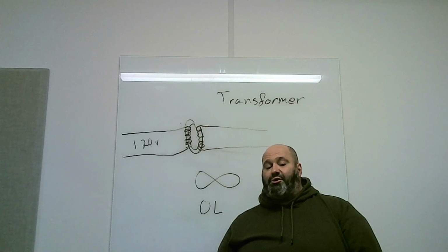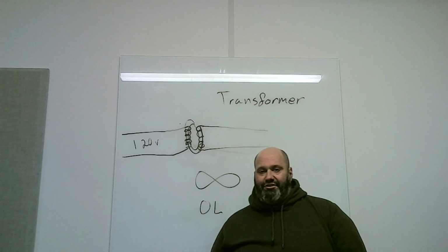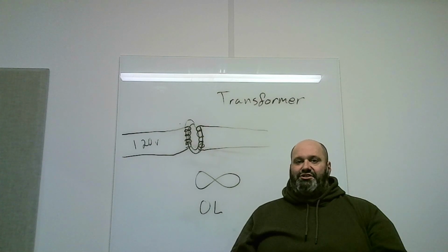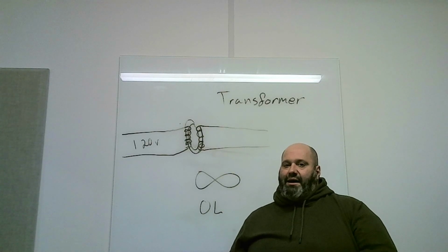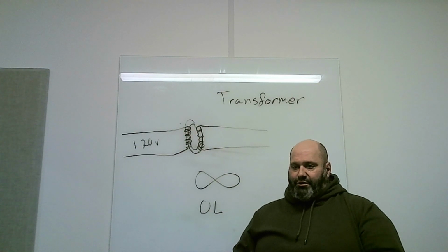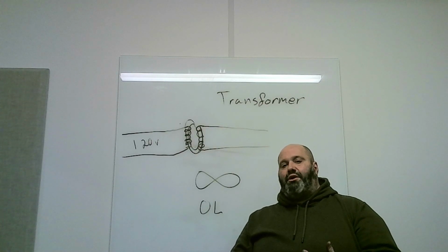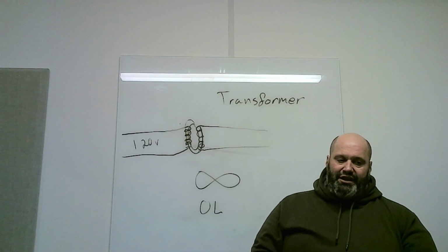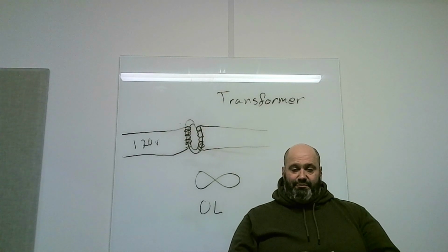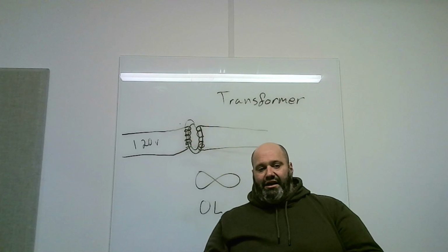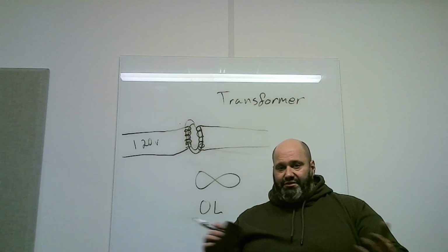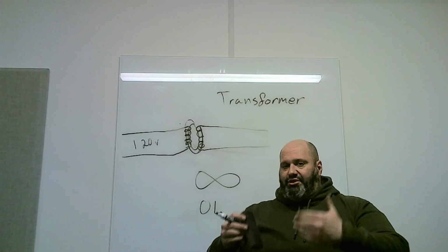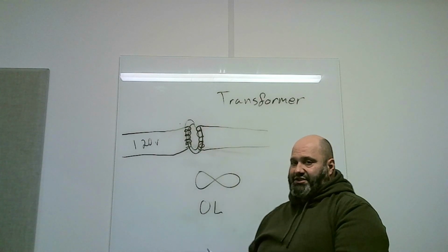You can't really repair a transformer, although I would presume technically anything is possible. Without the transformer, your system is dead. It cannot operate at all. So that's why it's important, before we're disconnecting wires, before we're going through and diagnosing anything, and really, technically, even if we're jumping out the thermostat or bypassing the thermostat in order to make heating or cooling mode turn on at our whim for testing purposes, we really should de-energize the transformer before we do that.